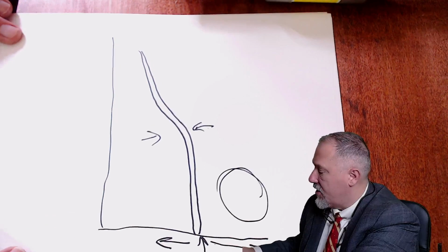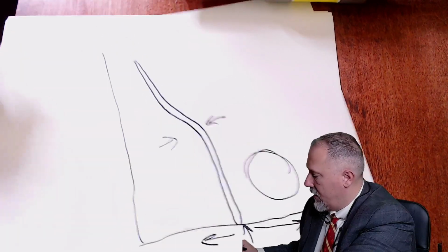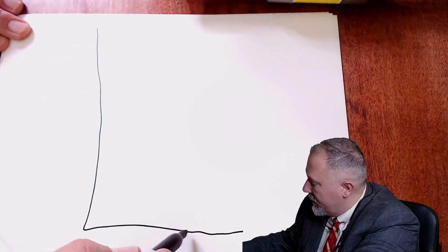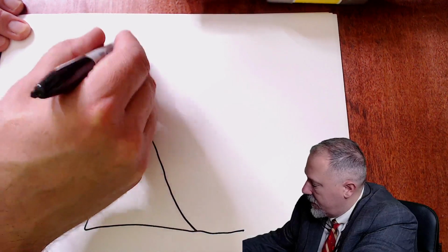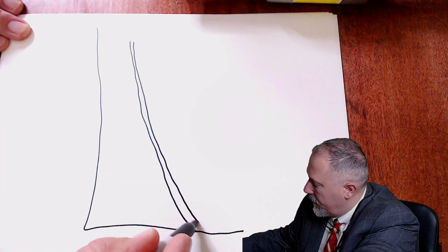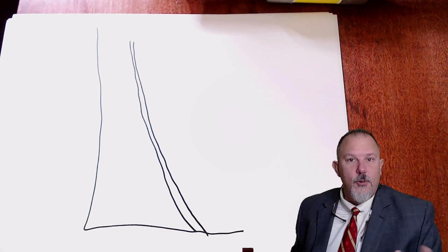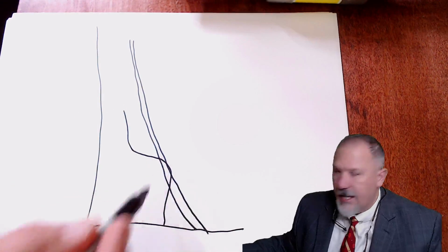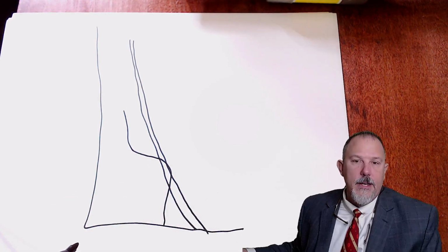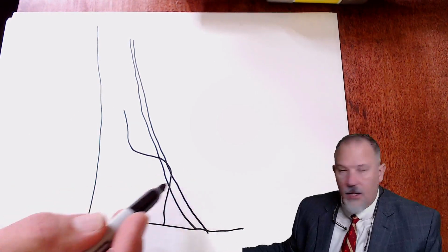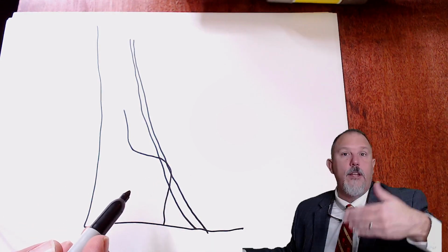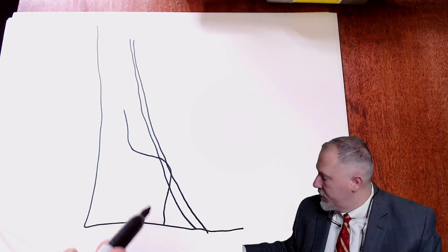Now, let's contrast this with what we call a fast-acting device. A fast-acting device will look something like this. You'll notice there's no knee. So if I have a motor inrush curve and it goes like this, I can accidentally open my fuse. I might need that little bit of a delay. That's a fast-acting device. It's not intended for motor starting or transformer inrush and things of that nature.